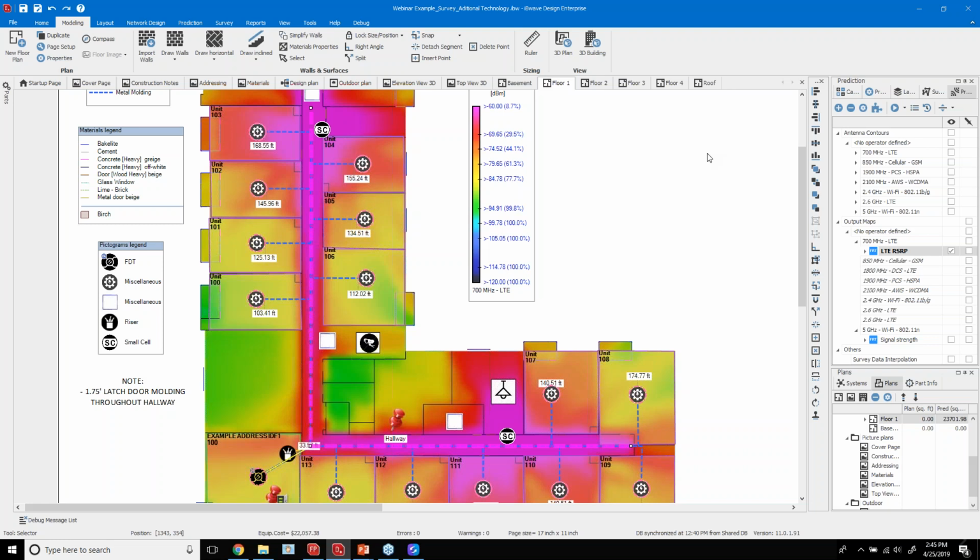David, this one's for you. What about use of single mode versus multi-mode and future proofing even if the distance is under 1,000 feet? Sure. So what's typical for a fiber to the X, fiber to the home deployment is the use of single mode fiber. FTTX is typically an outside plant deployment with longer distances. The multi-mode fiber solution just doesn't allow you to propagate your signal far enough without dispersion. So you have to go with a single mode in the outside plant.